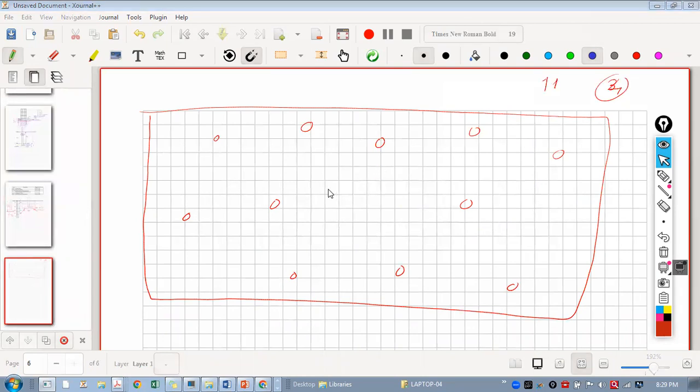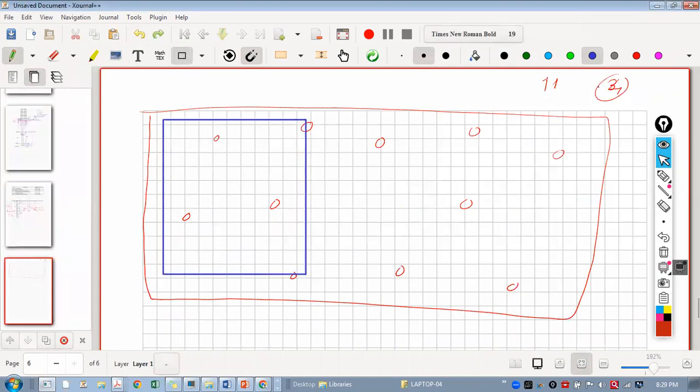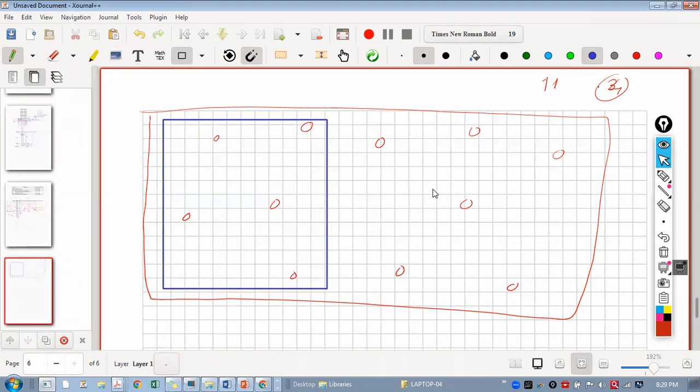So let's say your building is here, for example, somewhere here. And here the structures are there, but they do not have more loads. Then in that case, I would suggest, if the 11 boreholes are decided by them, see this happens within the communication between the client, architects, structural engineers and geotechnical engineers. If we are in the communication, then we can tell them to have more bore logs here, because this is the more footing area, we can say building area.